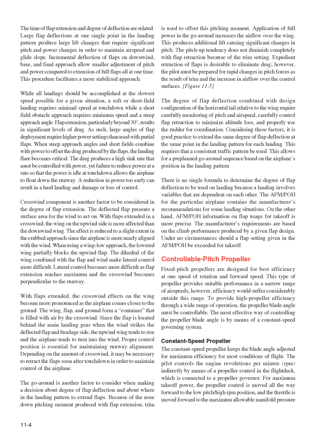Expedient retraction of flaps is desirable to eliminate drag; however, the pilot must be prepared for rapid changes in pitch forces as the result of trim and the increase in airflow over the control surfaces. Figure 11.5.